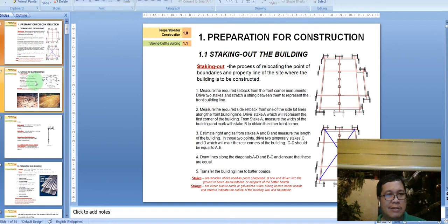But I think there's something that's missed here, which is a subject for debate, especially for those who are environmentally conscious. After you have done excavating the holes for the foundation, for the footings, you're going to do soil poisoning, so that there won't be any termites, bugs, or insects in the area.